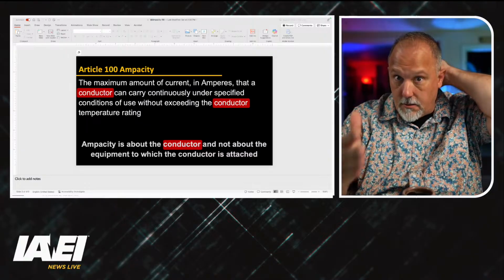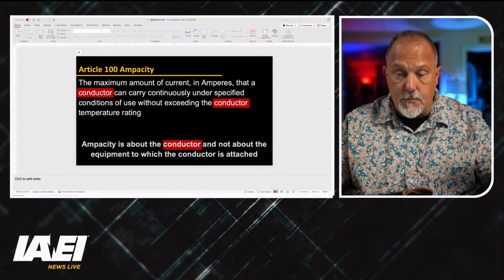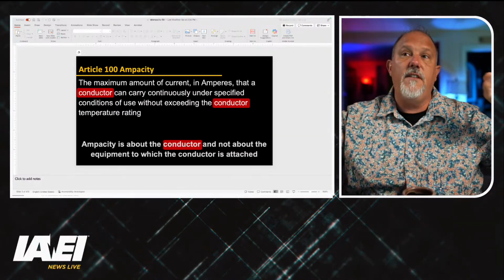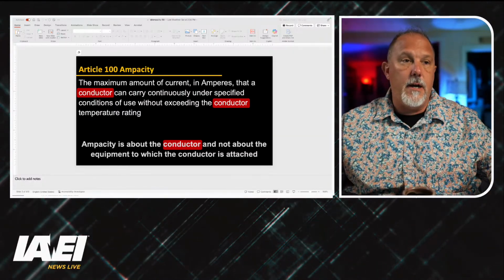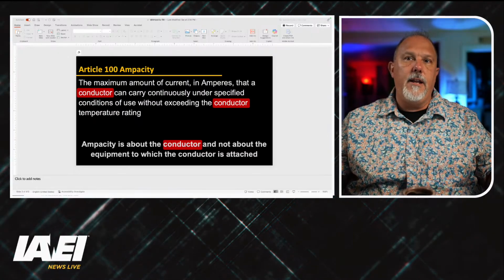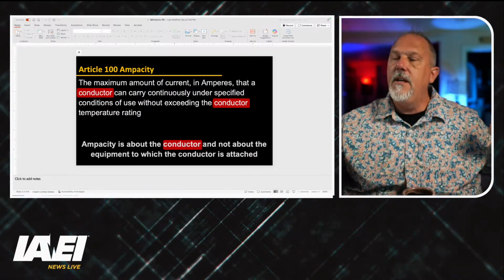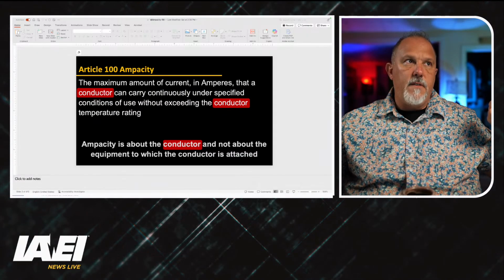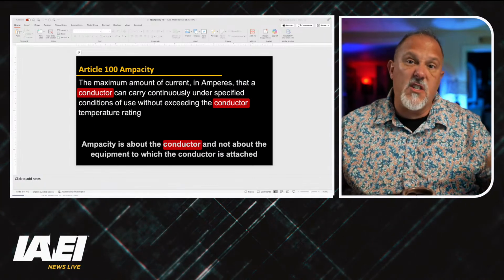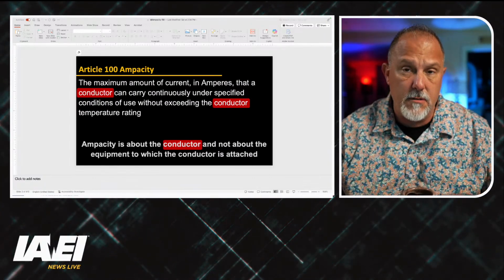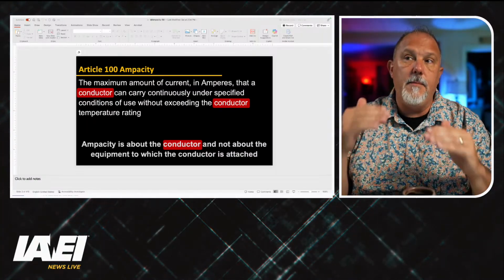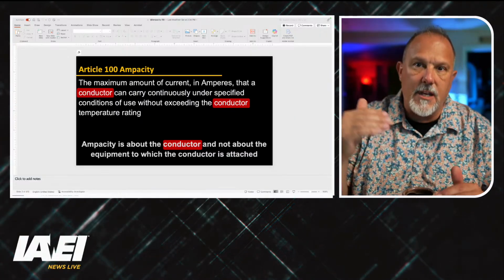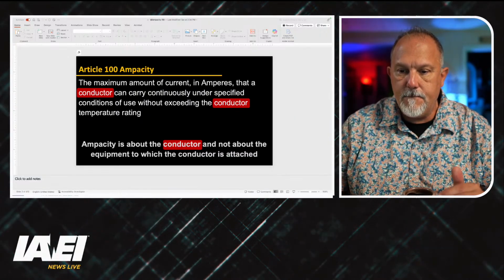So now we're talking conductor protection. A conductor can be protected at its ampacity, which, if I take a THHN conductor and I put it in an environment of 120 degrees Fahrenheit, if I put it in a raceway with 5 other conductors, now I am impacting the ability of that conductor to carry current, right?